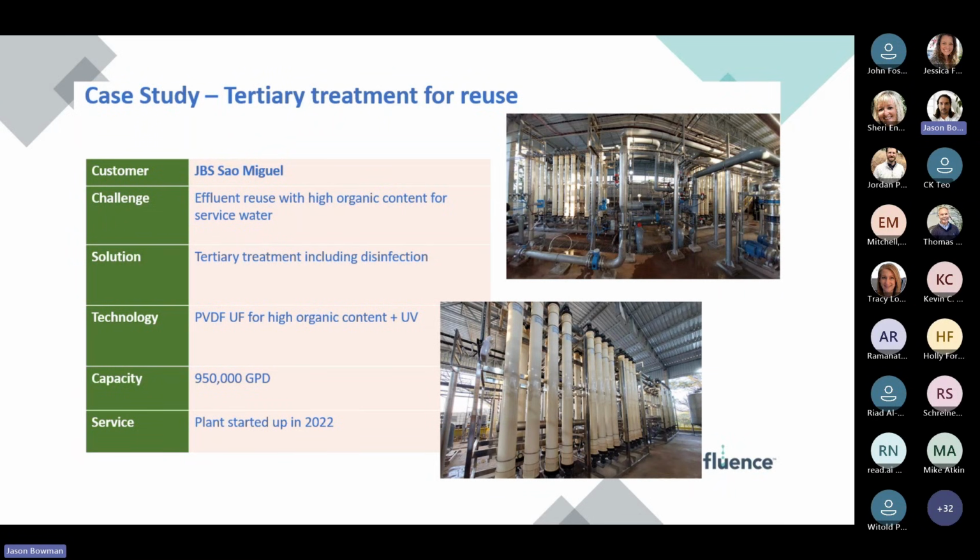So to, let's say, combat the impact to the local municipal water infrastructure, again, really lack thereof, Fluence and JBS partnered to develop a reuse strategy, which basically resulted in the construction of a brand new water reuse plant at the factory. The wastewater portion initially consisted of your conventional primary treatment, biological treatment, with those byproducts and biological sludges and DAF sludges going to a digester system.